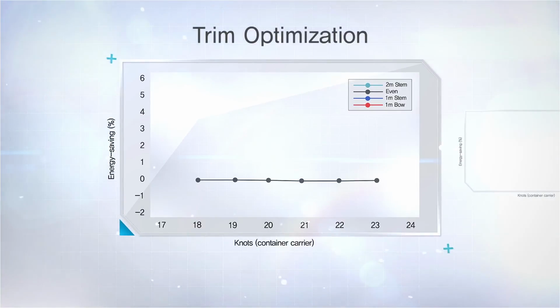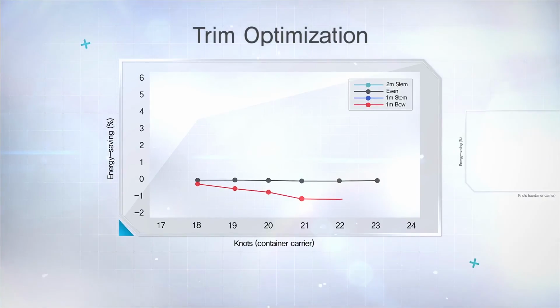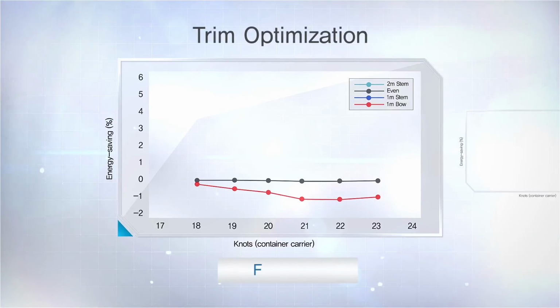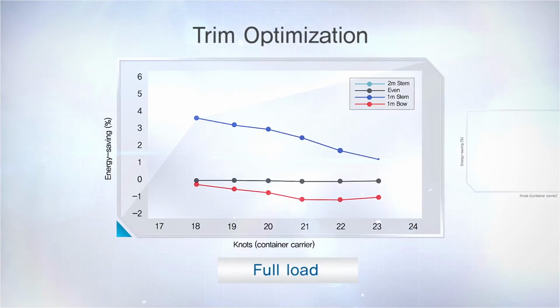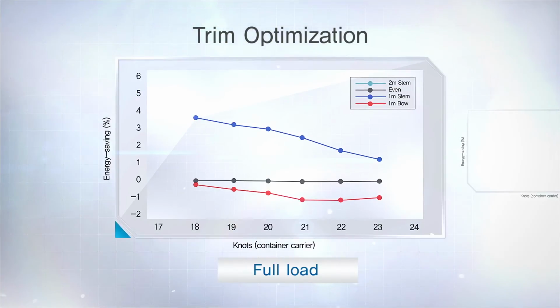An accurate prediction of trim is quite important because there is a fuel optimum trim. CFD simulations in full scale are recommended to assess the best trim. By changing the trim in the 6 different speed range, computations were performed at full load and ballast.